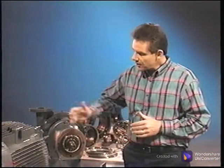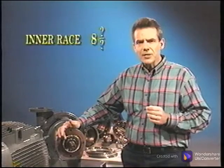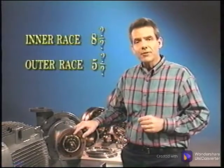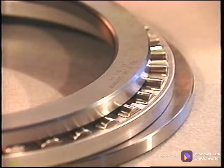We see here that the inner race frequency is also non-synchronous. Notice that the inner race frequency is 8 and a fraction, whereas the outer race was 5 and a fraction. Unless the bearing is a unique thrust design with a 90-degree contact angle, the inner race frequency will always be a higher frequency than the outer race frequency.